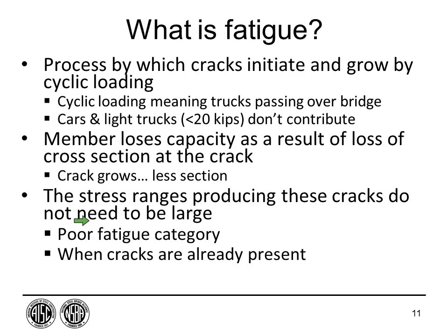So the first question is, what is fatigue? If you sit and you have a paper clip when you're bored and you keep bending it back and forth, eventually you end up with two pieces of paper clip. And that's really fatigue. It's a mechanical process where we begin to damage the material, usually at locations of high stress, and these defects grow by cyclic loading. So it's a lot different than strength.